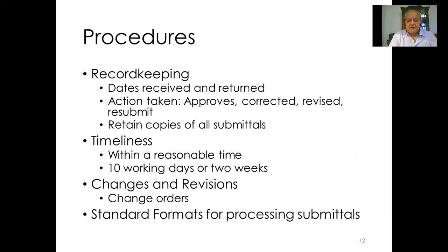So any letter you send or receive, any drawing you send or receive, you have to keep a copy. Record keeping is very essential. Most projects end in court. People at the end will have some problems. It can be very big problems, can be very small disputes. But any project ends with this. So you have to make sure that you have all your supporting documents of everything you do in the project. So record keeping is extremely important to save yourself from any penalties at the end.